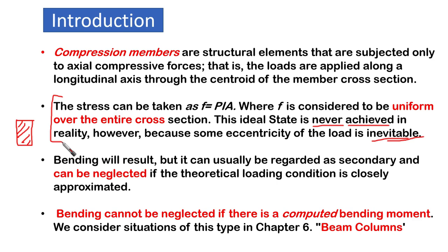Bending will result in this case; as long as there is some eccentricity, there would be some bending that we are expecting to take place. But it can usually be regarded as secondary and can be neglected. That's very important. There is an additional moment, but we are going to consider it secondary and neglect it.